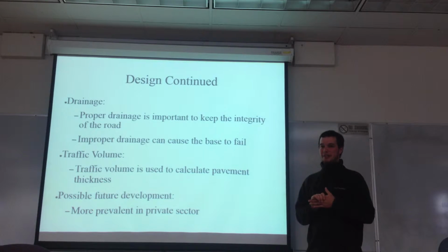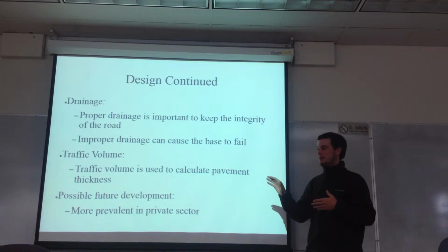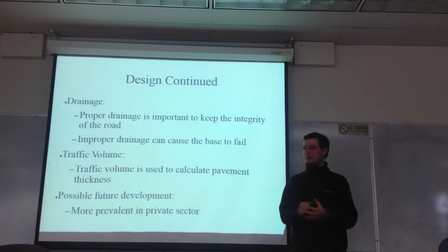Next we've got to think about traffic volume. Now, for traffic volume, we'd have to go into more detail than I can in a 10-minute presentation, but traffic volume goes into the design equations for the pavement. So we can't go into that too much, but it's very important to study the traffic volume. A lot of this is done with historical data, so we can know how thick to design our pavement.